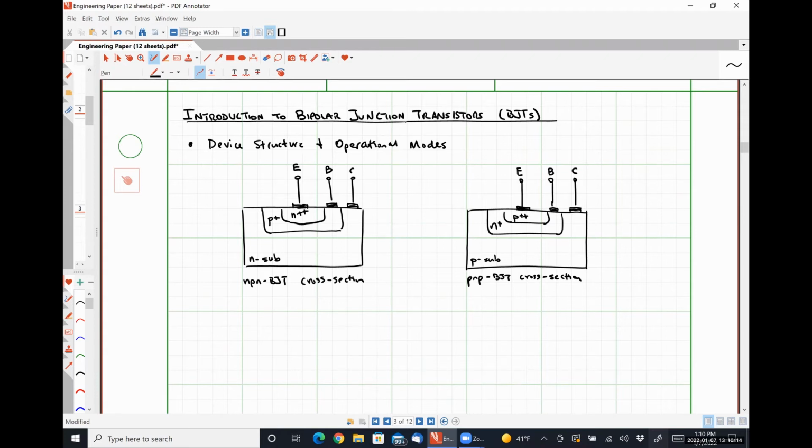Yes. So the width of the base for a modern BJT is on the order of a couple of nanometers. So it's rather tiny. And the full reason is because we need to ensure that not all of our charge carriers recombine before they hit the collector. Because if they do, the amount of current that we could ever see flowing through this thing is going to be based on a very tiny recombination current instead of a reasonably large diffusion current that we can sustain with that base emitter voltage. Does that make sense?